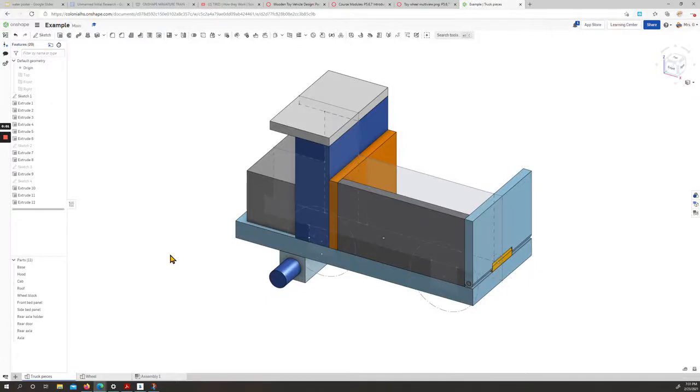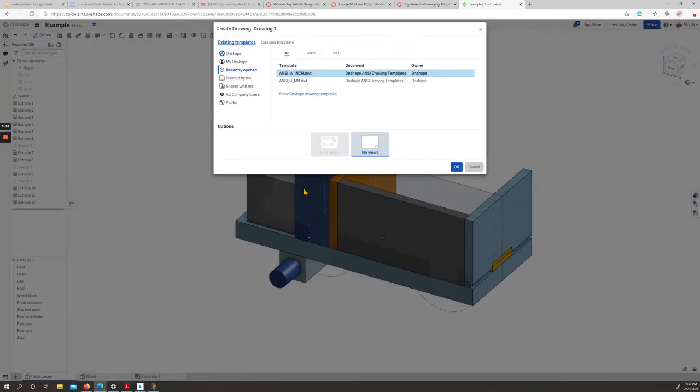In this video, we are going to talk a little bit about creating drawing files. So for our activity where we've created the general pieces of our vehicle, we do need to create drawings of our major pieces. What I'm going to do here is go to our Insert New Element plus sign in the bottom left corner. We're going to choose the Create Drawing option.